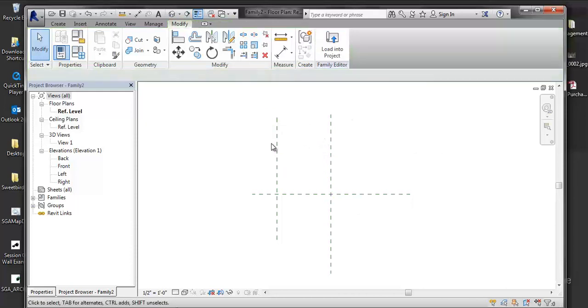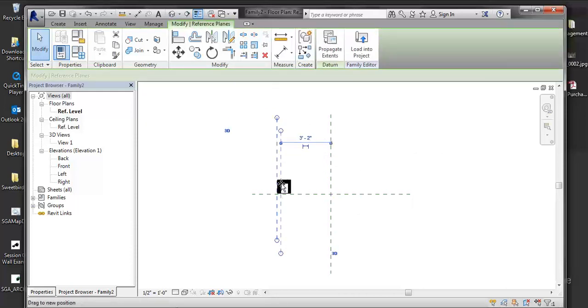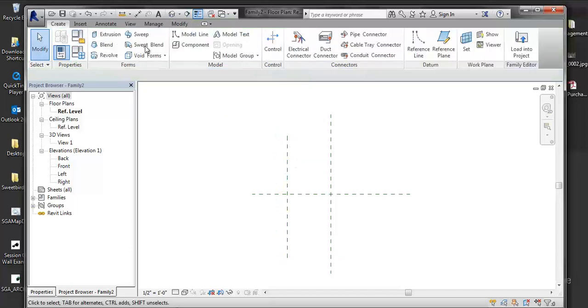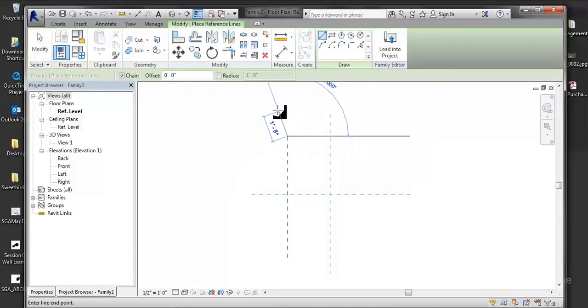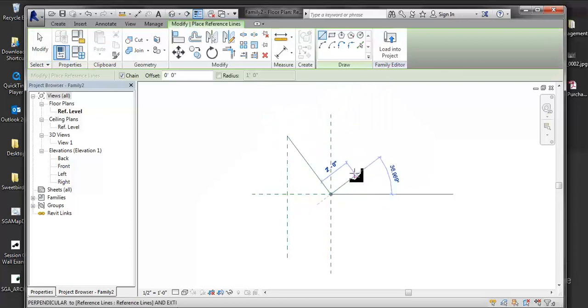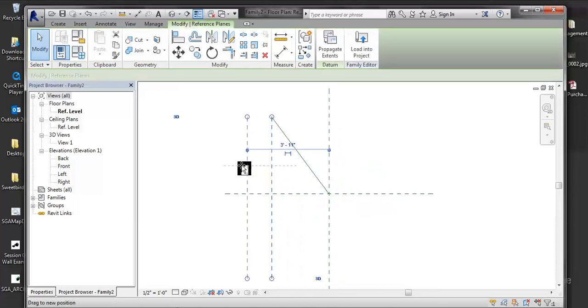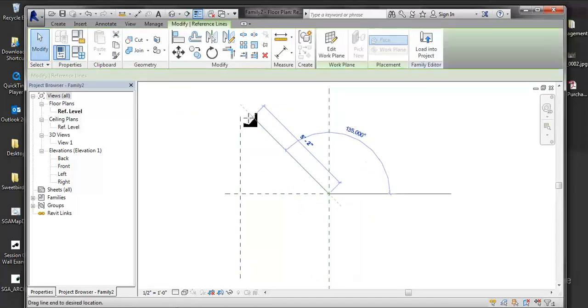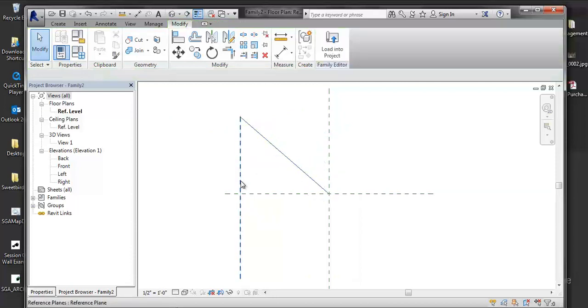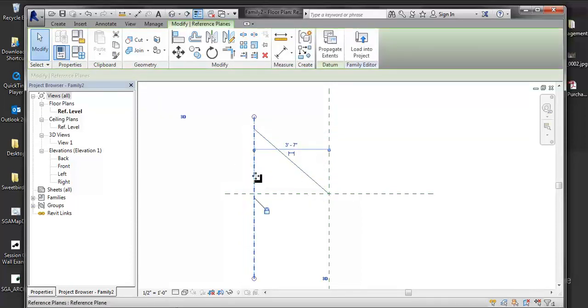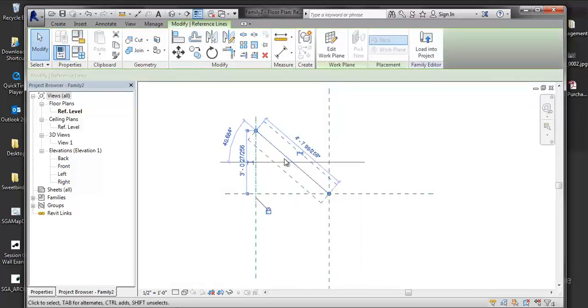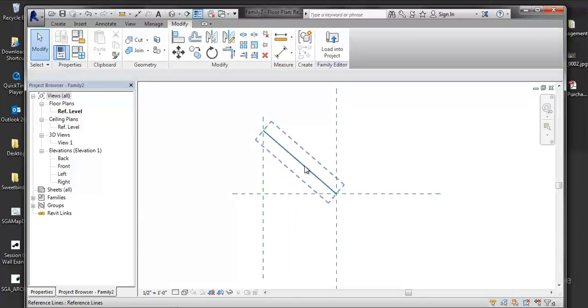Now if I wanted to constrain an angular element and build off angles, I would go to Create, Reference Line, and then the reference line acts similar to a reference plane, but it does give me a start and end condition, right? And it will snap itself. So I need to actually formally snap it by locking it. Then when I move it, it'll cut itself for me. Can you hinge the connection? Yes, I can. And we'll do that once we get into editing here. But yeah, you can hinge the connection.